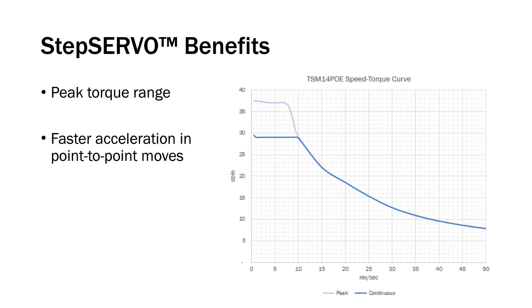Or if the motors aren't running all the time, your power demand is going to be less. So you could potentially run 4 motors at the same time as long as some of them are resting while others are moving, so that you stay under that budget. Generally speaking, what I've seen is the energy budget.